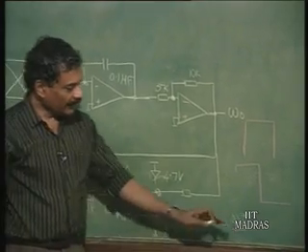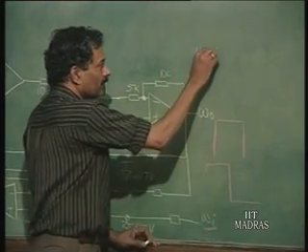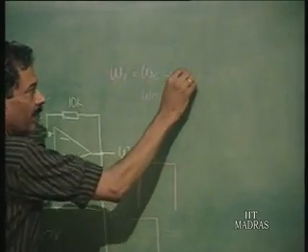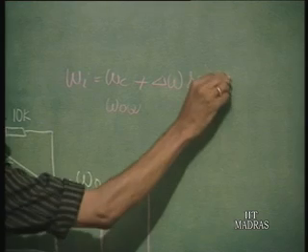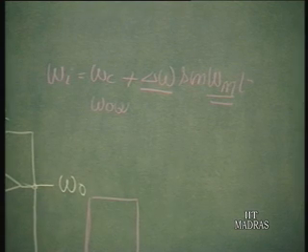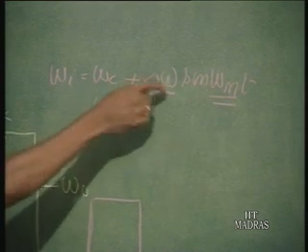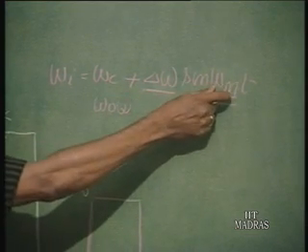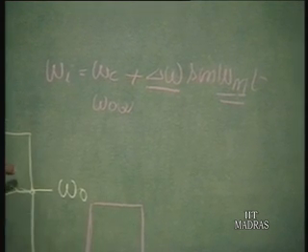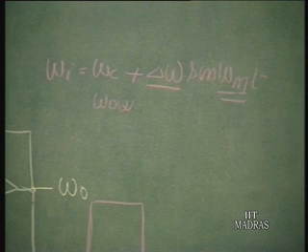And then as I vary, there are two frequencies here. One is the frequency deviation. So, omega i is going to be omega c, which is close to omega naught, plus delta omega sin omega m t. This is a low frequency, okay, modulating frequency. This is the frequency deviation. I will change the deviation, okay, and show that it is going to track that, and this deviation can be changed faster or slower by changing this frequency. Okay. So, this will demonstrate clearly that the FM inputted here is going to result in an FM at the output. All these demonstrations will be now done, and Devaki will show you the output of the